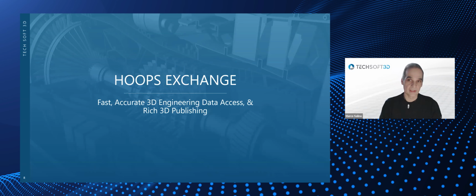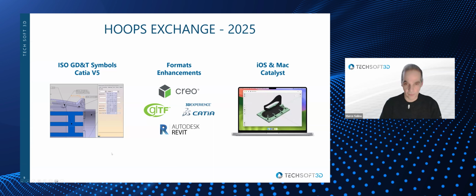It's not just simple file translation, as a very important point to consider. With Exchange, you can access data from over 30 CAD formats performantly and without any dependency on these CAD formats. We can access BREPs, tessellation, metadata, PMI, and you can transfer the data you need into your own structures with very high fidelity. Of course, you can also use Exchange for file translations, as we can export to over a dozen formats. It's also worth mentioning that Exchange can perform geometry adaptation, point projections, clash detections on imported data. So it also allows for more advanced operations.